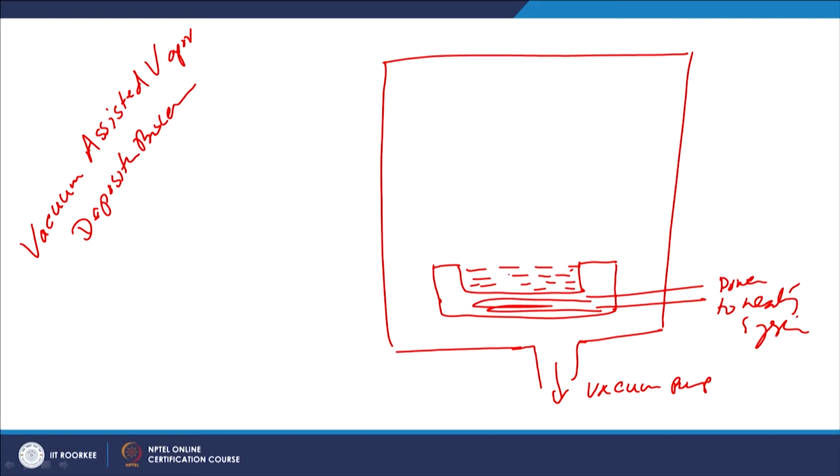The coating material is brought to the molten state, and due to the higher heat, it is evaporated. So the gases which are formed or evaporated from the molten bath will be moving up at low velocity towards the surface of the substrate.